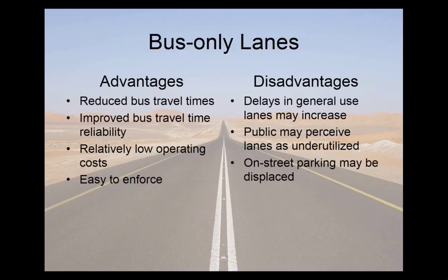On the other hand, delays in the general use lanes might increase due to the presence of bus traffic. The public might perceive the lanes as underused and therefore demand that they be converted to general use. And also, on-street parking may need to be removed to make way for the bus-only lane.